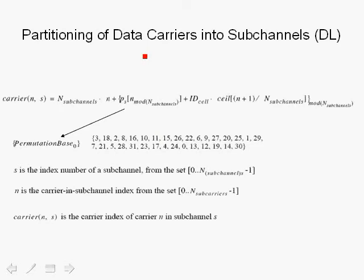So let's talk about the partitioning of data carriers into subchannels, and in this case we will focus on the downlink, which is transmission from the base station to the subscribers. Now this is based on the 802.16a recommendation. This formula looks kind of complicated, but it is not actually. Let's explain exactly what is going on here, and we'll give you an example. S is the subchannel number, which will range from 0 to 31.